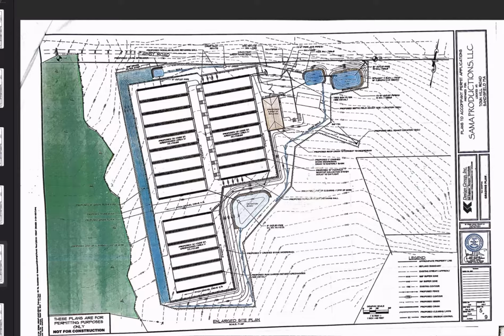The driveway shall be crowned. That's just site grading. So our driveway will be crowned. The driveway has to have a culvert to control water. We have a 15-inch, let me double check that. I'm not sure I labeled it there, but I'm pretty sure it's a 12 or 15-inch culvert that goes under the site driveway. Cuts and fills, I've designed the driveway so there are really minimal cuts and fills, maybe a couple of feet at worst, but very much matching grade.